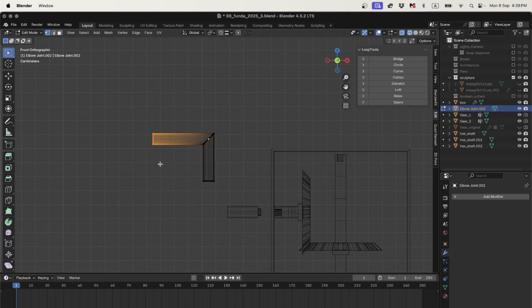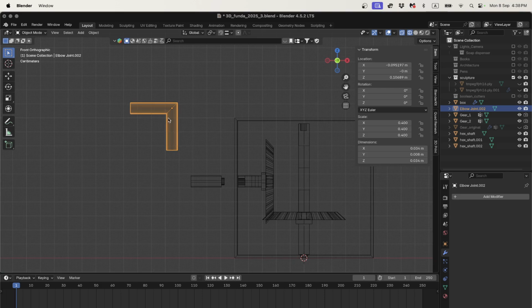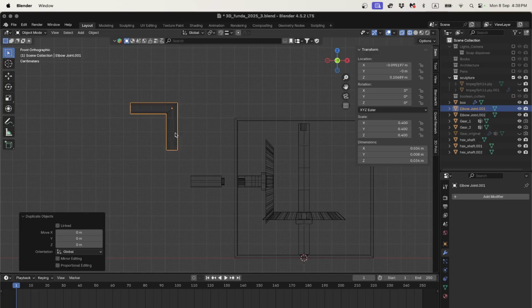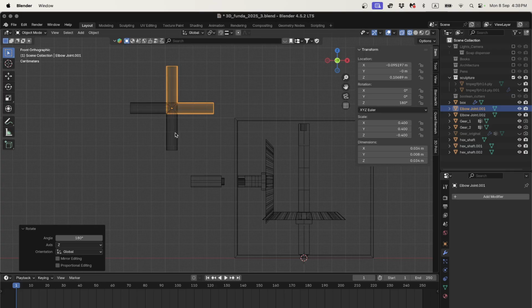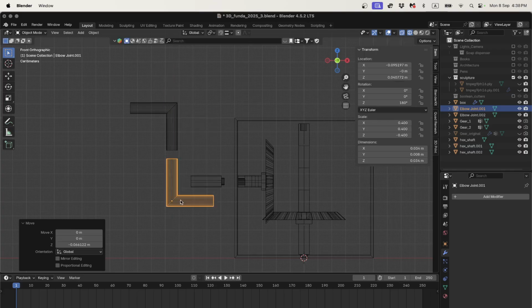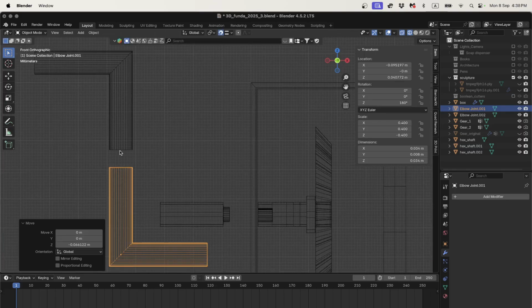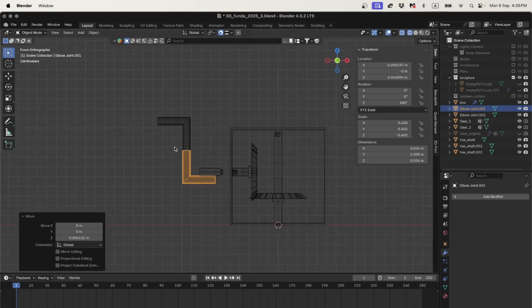And here I will GX 0.01. Okay, so we're still symmetrical on that. I think that should be a better size. So I'll just mirror that as before. Shift D and then left click straight away. Scale Z, SZ -1. Rotate Z 180, enter. Then GZ, bring it down, and then I can turn on my snapping and just GZ, snap it up.